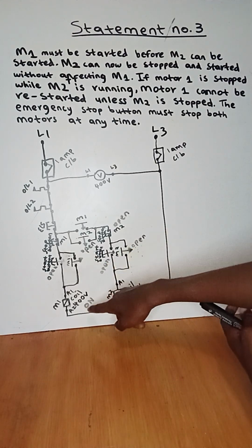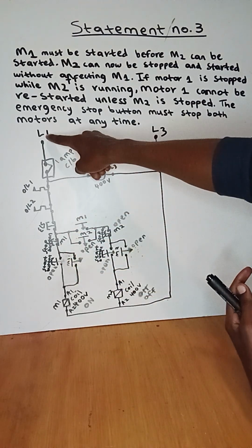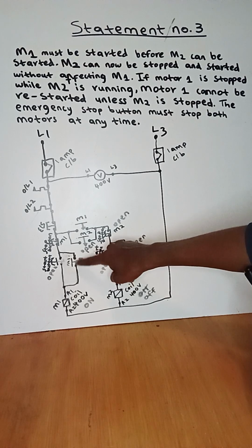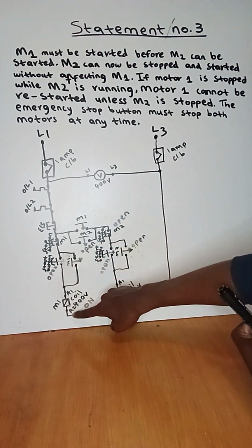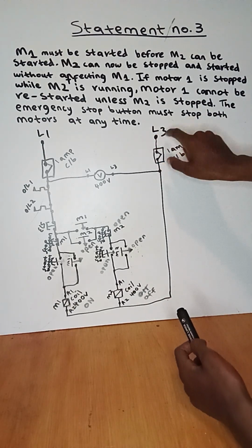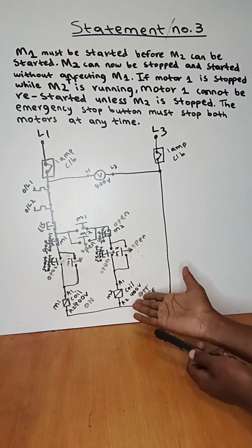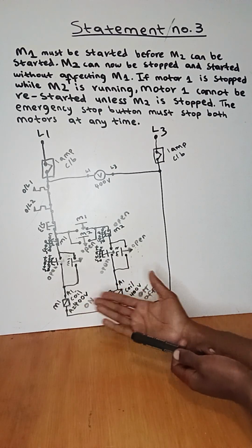So from motor 1, let's check if it gets live 1 and live 3. From live 1, current flows down here and all the way and finds the retainer of motor 1 closed, and all the way to A1, and from A2 it also gets live 3. So it's still energized. It didn't affect motor 1 to be off.